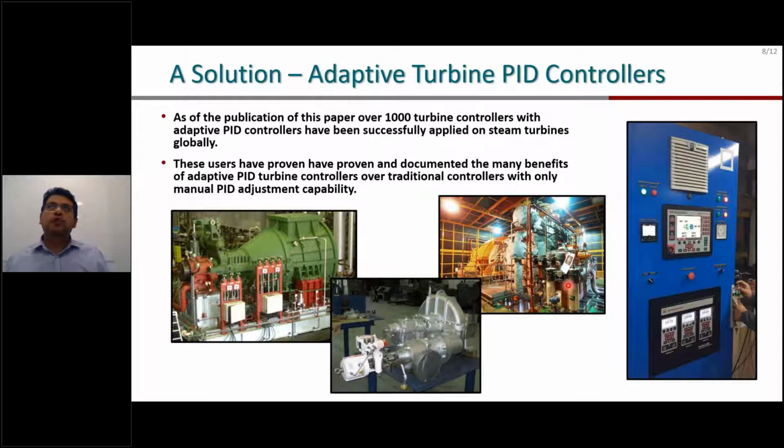That the controller itself, or the machine itself, has been through different scenarios, so that it is able to learn properly. Otherwise, it will give you values based only on the scenarios that it has been through. But if you have the controller built inside the controller, the PID or the adaptive PID tuning, what you will have is that the scaling and all this intricacy, all this calculation is done internally within the controller.